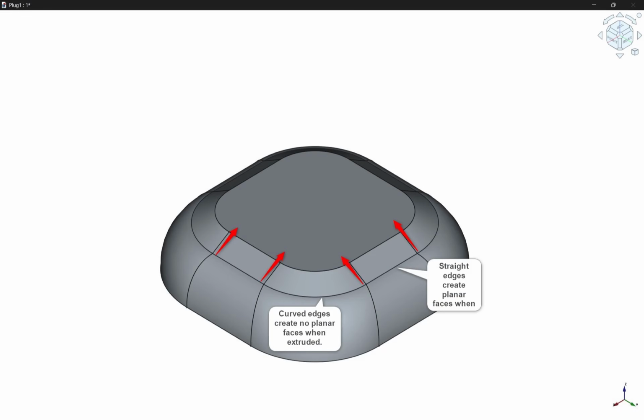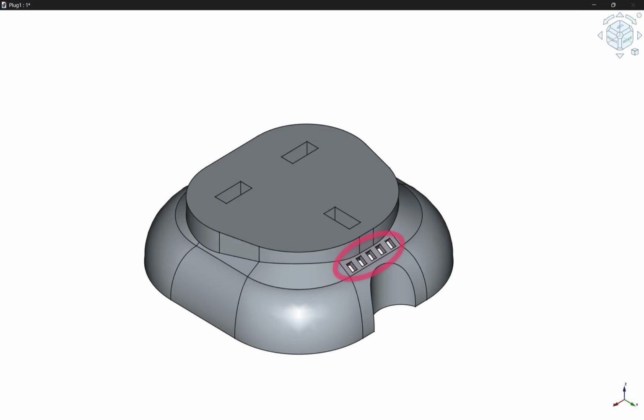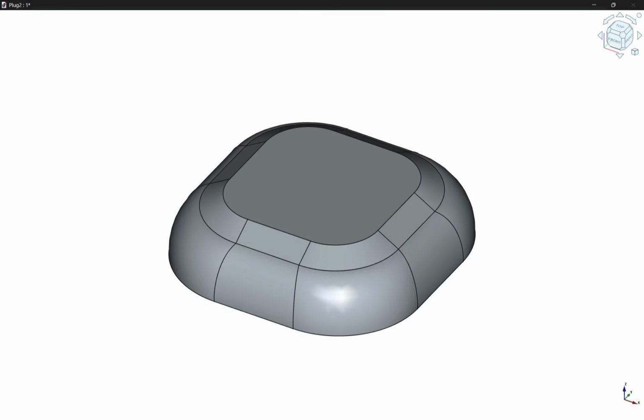This is because it consists of straight edges, which in the future allows sketches to be attached to the resulting face for additional features and detailing, such as ventilation holes. With a non-planar face, we would have to use advanced attachment modes. But we're making the model increasingly more complex to hollow out. So let's take a step back in our process, focusing solely on the loft and the tapered pad.